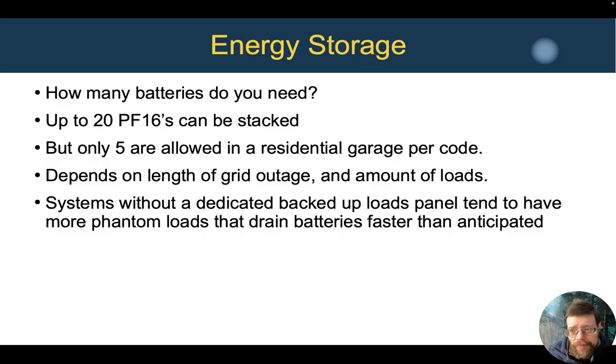But if we're doing backup power for a typical house, we need to think, how much can 80 kilowatt hours really do? If we're just running lights, power for controlling a propane or natural gas fired heating system, and say internet, fridge, miscellaneous stuff like that, it can do quite a lot. If we start trying to back up heat pumps or any sort of electric heating appliances, 80 kilowatt hours doesn't go very far.